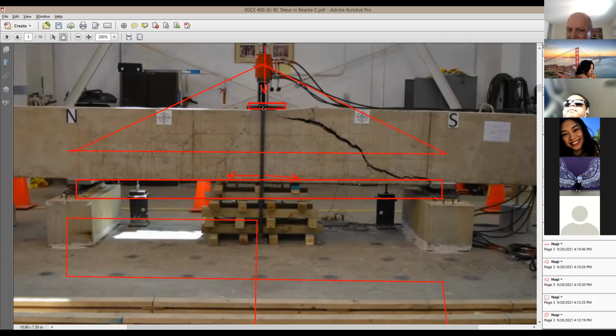So this is like the mechanism to apply the load. It's a little bit different from the standard point load that you may look at. So it is not really a support. It's not a support as a beam. It is a mechanism to apply the load on top of the beam. So this jack here wants to pull this rebar up. While it is pulling it up, this jack itself is pushing down on the beam. Does this make sense or no? Yes, thank you. Okay, no problem.